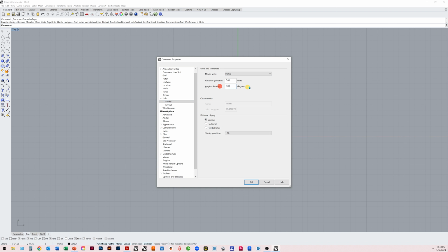We're just going to match what I have here. And then we want this in feet and inches. That allows you to use 1 foot, 2 inches, etc. And then we're going to change our precision to be super high, just because that's good practice. Okay. So take that units command bar and match this layout.